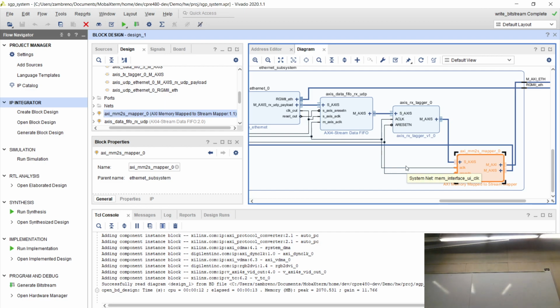You will eventually get pretty good at reading these signal names and recognizing what's there or is not there. AXI means AXI bus, obviously. Memory map was just another term for AXI full, so the full signaling that we're learning here. To stream, this is getting converted to an AXI set of stream signals, and it actually works in both directions here. This takes a set of Ethernet packets, or UDP over IP packets, sent on the Ethernet bus here.